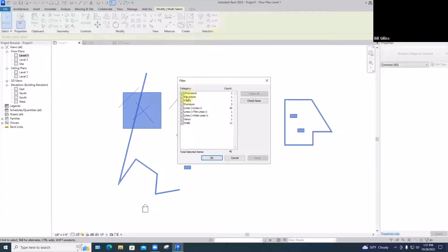I'm going to leave them checked. So let's just say I'm going to leave just furniture checked. It might be lots of different kinds of furniture, some chairs, whatever. Select all instances in view would pick up all the desks, but not all the sofas and everything at the same time. So if I just leave furniture sets checked, so then okay.